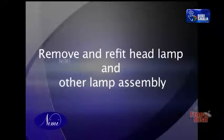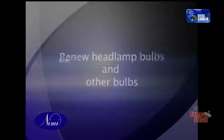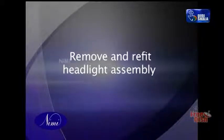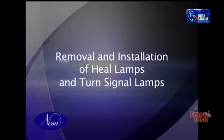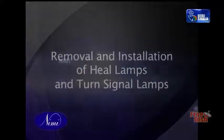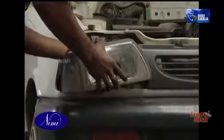Remove and refit headlamp and other lamp assembly. Objectives: renew headlamp bulbs and other bulbs. Remove and refit headlight assembly. Removal and installation of tail lamps and turn signal lamp. Disconnect the headlamp connector. Installation is the reverse of removal.